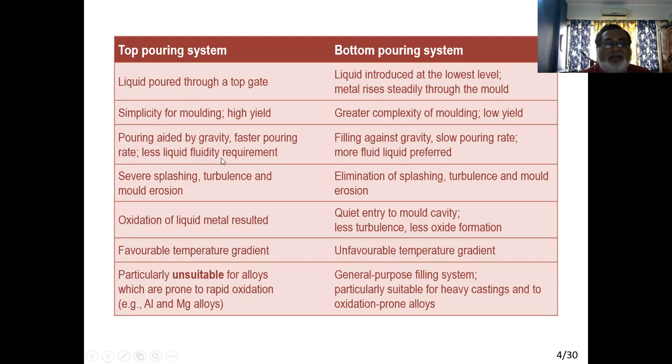And in that period of time, the only two metals commonly used were steels and cast irons. These types of alloys have low fluidity. So one purpose of casting was how quickly we can fill the mold cavity. Fluidity is an issue because steel solidifies very rapidly. As a result, top pouring is always preferred, and in all the gating systems used in those textbooks, you will see the top pouring system.